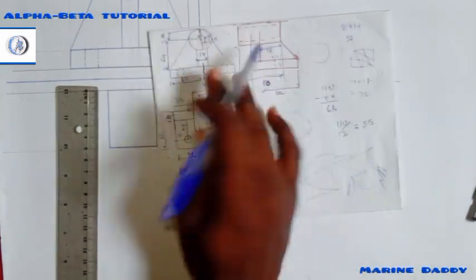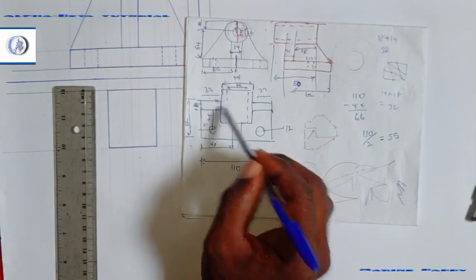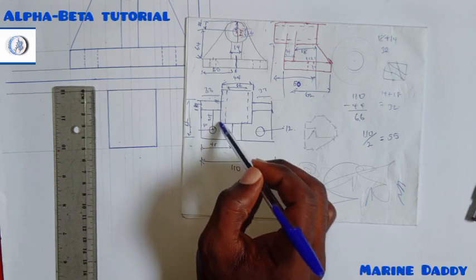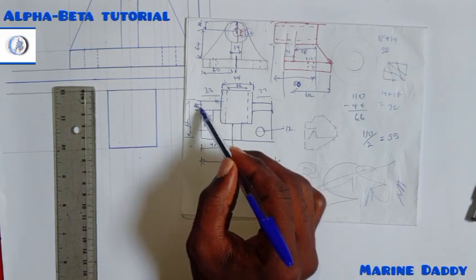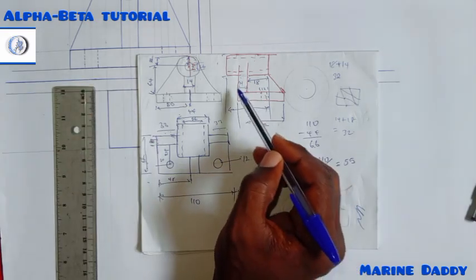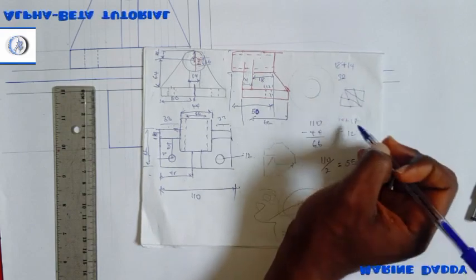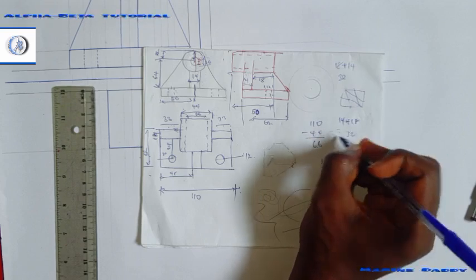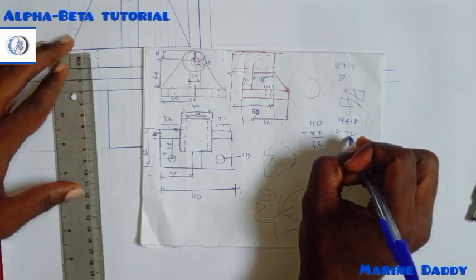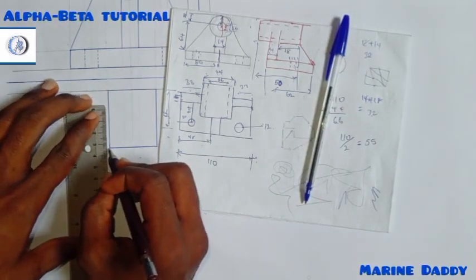Okay. Once we are done with this part of the diagram, we can go over to this side. From this part to this side, they did not give us the actual calculation, but they told us that from here to here is equal to 14. According to our side view, we can see it. Remember, orthographic projections complement themselves. Since it's 14 and here to here is 18, 14 plus 18 gives you 32. So I just have to measure 32 from this place.